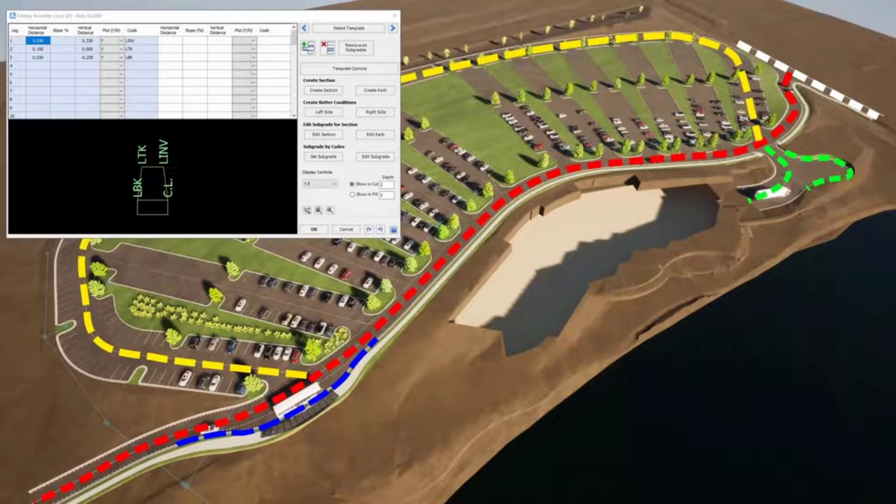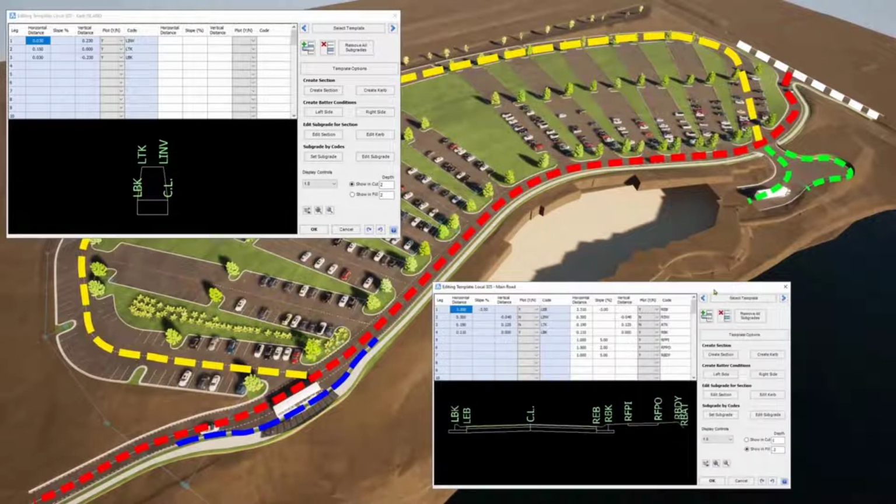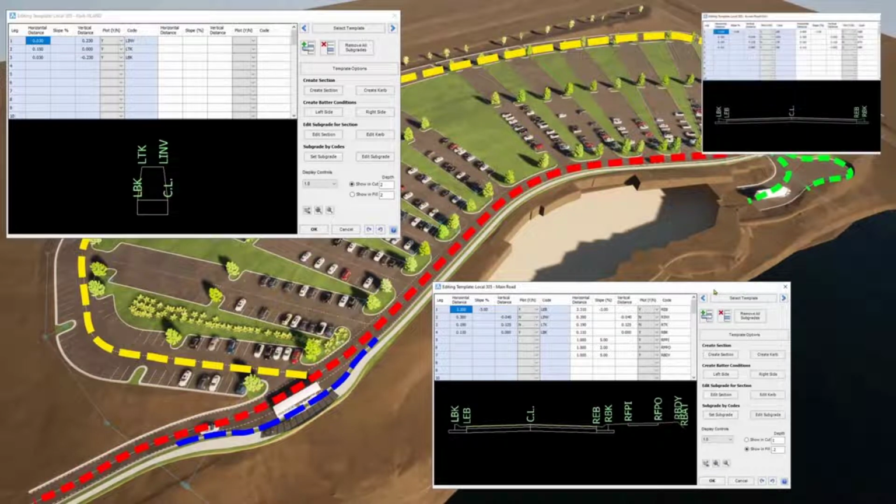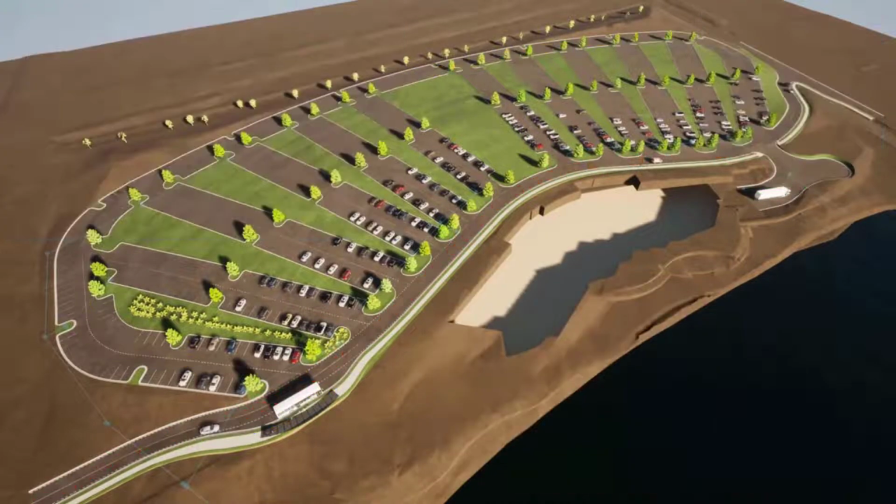So there's quite a bit to get done, and everything that's done here is done with templates which we've created already. As we build the islands in the middle of this, which is the main car park area, it isn't just the top surface, we're also modelling the boxing, so we have quantities of curb to be calculated as well. We have made templates as well, and they've been named as main road and access road, etc. So they are very obvious which one links to which road. There are other ways of doing this where you would use fewer templates and just do on-the-fly variations, but using this method, it makes it very, very easy to follow.